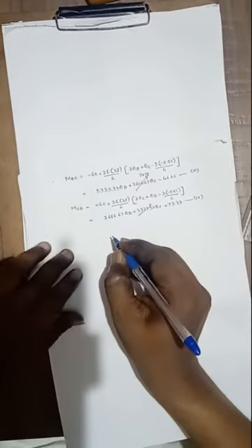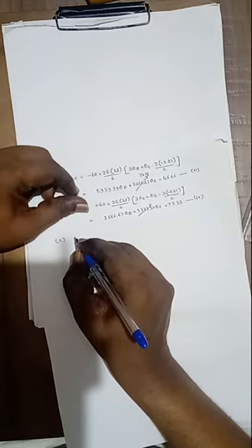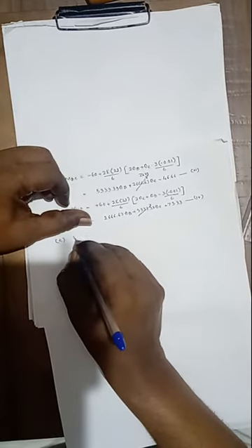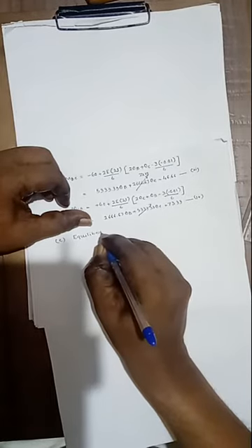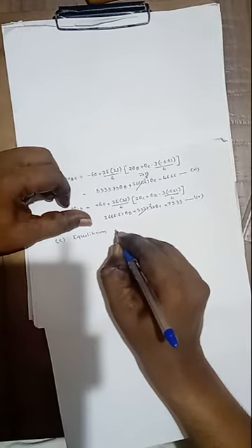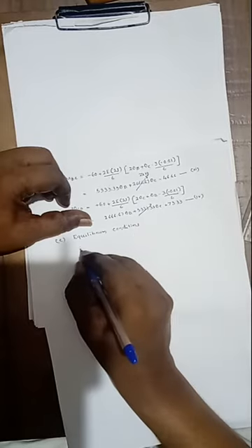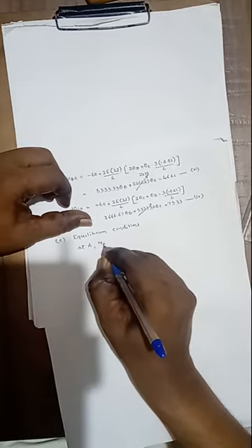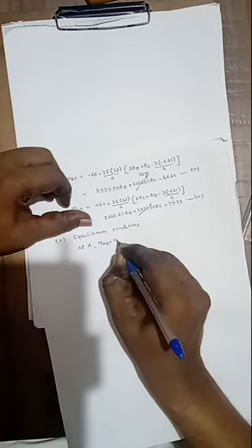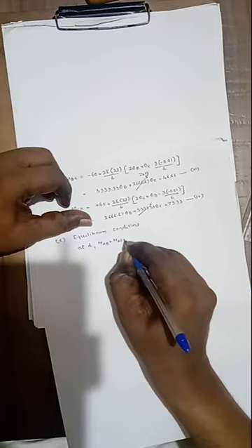Now we have got the 4 equations, that is 2 for each span, for AB and for span BC. Then by applying the equilibrium conditions of the supports, here at A there is one joint, MAB plus MAD equals 0.